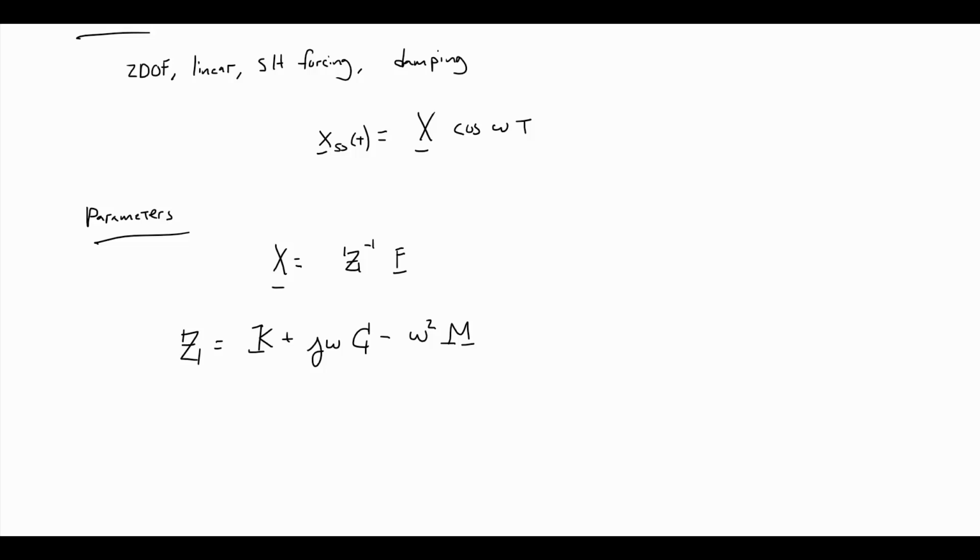I mean, it's going to come into play in that the natural frequencies are a function of the mass and the stiffness matrices, but we're not directly calculating them in order to find the steady state response. Because we're only looking at the steady state, the transient or the homogeneous part has already died off by now. That's affected by our natural frequencies. The steady state is only affected, at least frequency-wise, by the driving frequency.